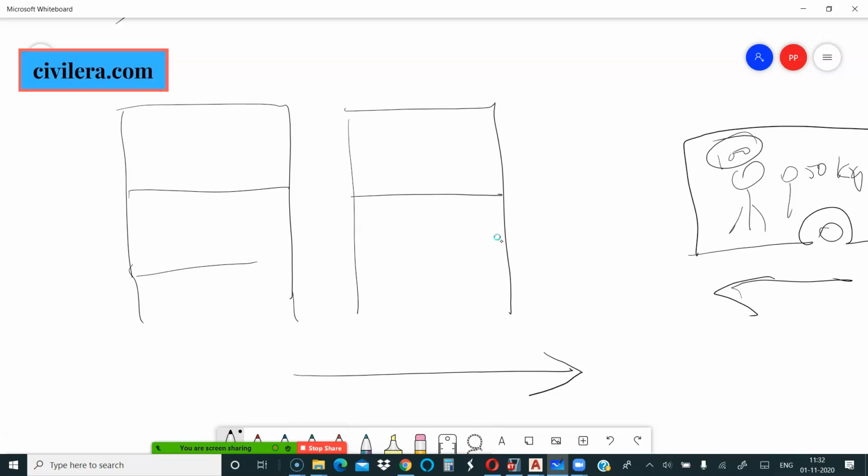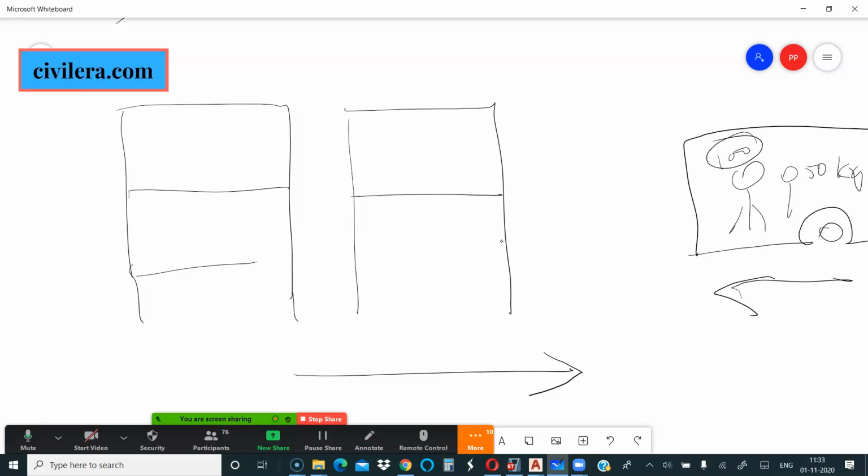So right assessment of load is very important for right behavior, right design, right detail, right experience. Don't think that giving more is always good. In the case of columns, maybe sometimes it may be good, but not for all members. If your slab thickness is increased to 150 instead of 100, you are bringing in more seismic demand for the building. You need to satisfy more inertial force, which means your columns are going to be over-reinforced than needed. So right estimation of loads is really important.